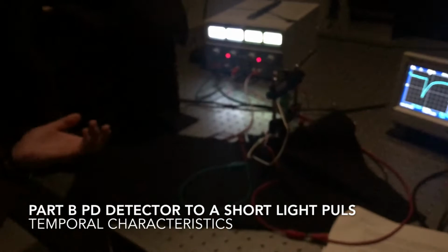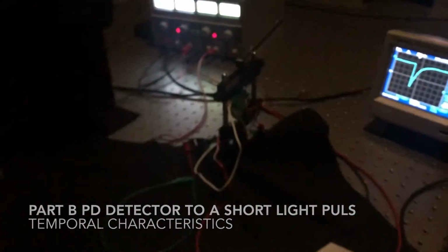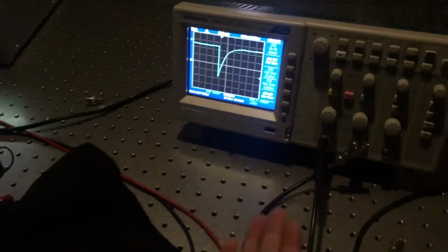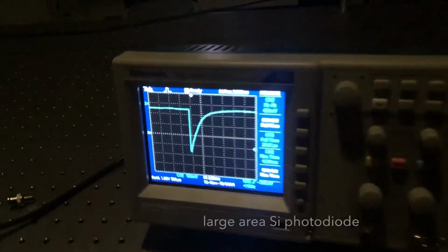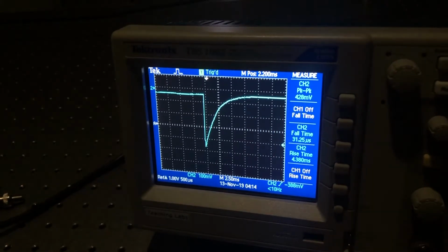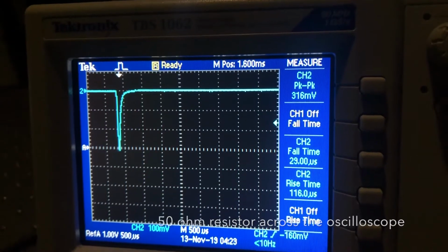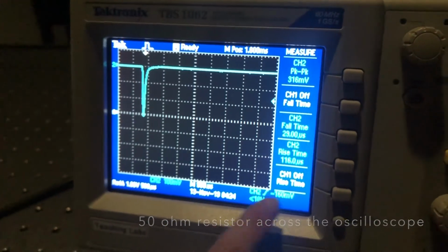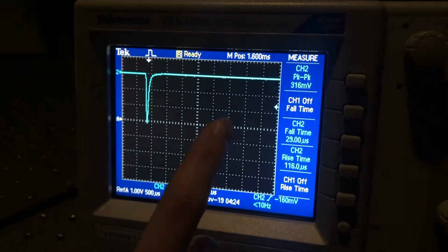So the purpose of this part of the lab is to determine the time constant of photodiodes in various situations. We did this by setting up the flashing fire alarm to go into the detector, which is attached to the oscilloscope. We set the triggering settings to show this nice graph, and then the rise time is the decay time because it's inverted. So for this one, we added a resistor, and it gave us a smaller rise time, which is the time constant, and a smaller peak-to-peak.